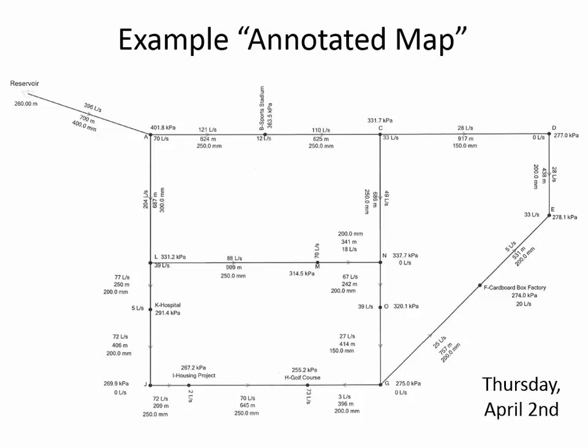You need to type that into the computer, right? You don't need to include it as an annotation, though. But you do need to tell the computer what's the elevation at the junction so that it can take that into account when it's calculating the pressure.